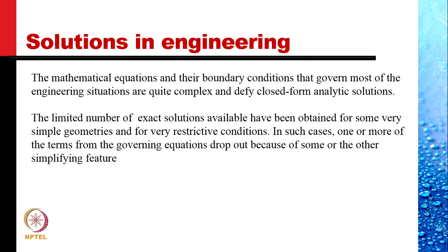restrictive conditions. In such cases, one or more of the terms from the governing equations drop out because of some simplifying feature, such that in fluid mechanics and heat transfer, it is common to make assumptions of steady flows, fully developed flows, one-dimensional or two-dimensional flows, low viscosity flows, negligible viscosity flows.